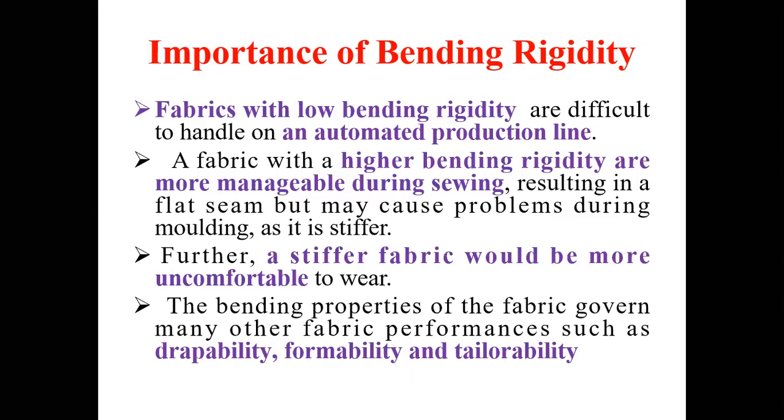Okay. Now, higher bending rigidity, in one case it is beneficial because there will be less chance of seam pucker. Also, it will be more manageable during stitching. But at the same time, if the bending rigidity is too high, the fabric will be, you can say, stiff, and the physical comfort of the fabric will be poor. Now let us see what is the mechanism of the bending.